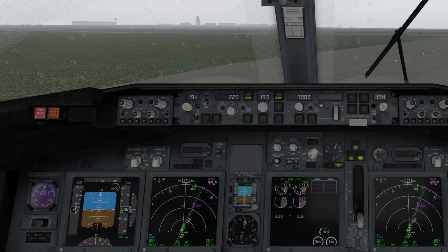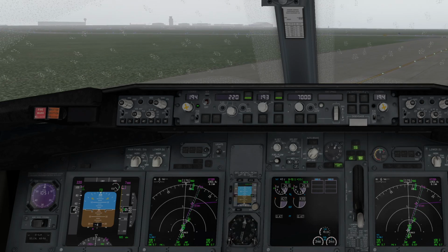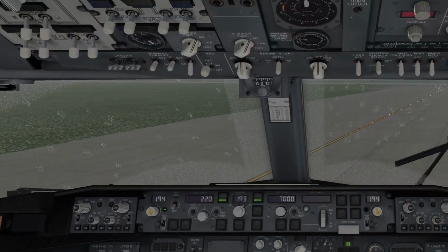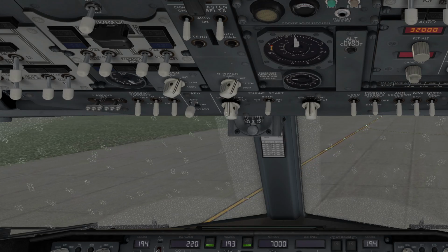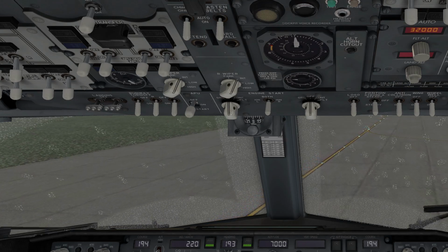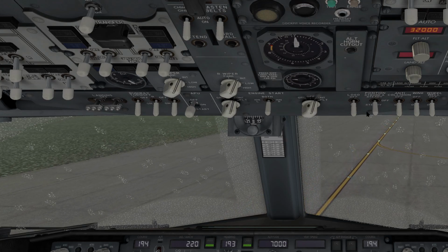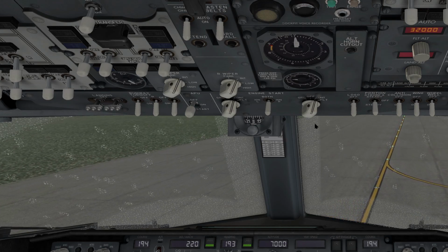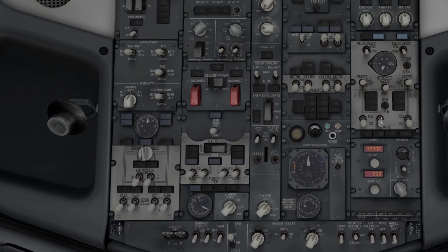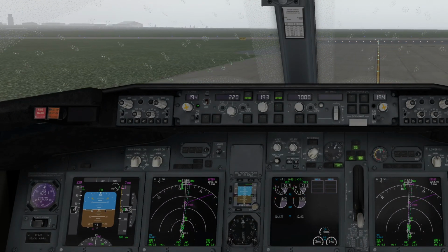Still need some thrust. Runway lights on, runway turn-off lights, start ignition switches to continuous. APU is off, so APU bleeder off, and we can start the clock.